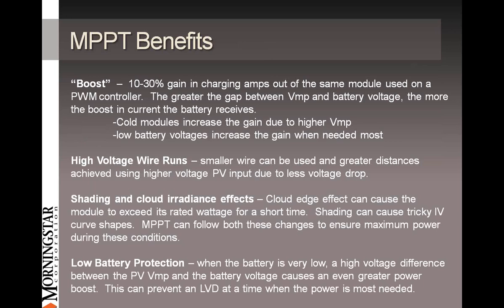So the bottom line for the benefits here, what we mainly try to focus on, is the theoretical boost, in quotes, not the power you're creating, because we're not creating any power. You're just getting more power out of the module that you should have gotten from its wattage rating over and above a PWM controller. So I'll just use the term boost lightly here. 10 to 30% gain in charging amps out of the same modules versus a PWM controller.